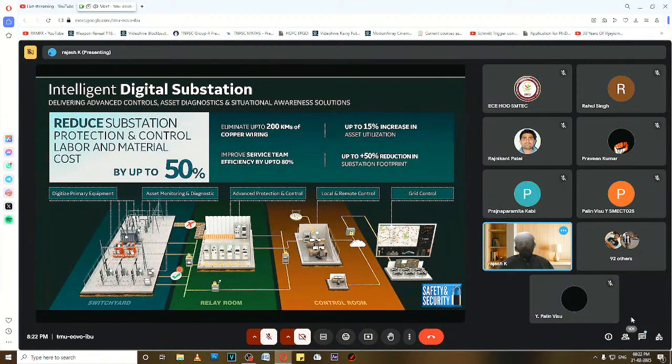Then we switched to monitoring and diagnostics in an advanced digital substation using several sensors, like temperature sensors, moisture sensors, and dissolved gas analyzers for the various gases which cause damage to the transformers. And we discussed the OLTC, and thermal cameras as well. Hope you find it helpful and interesting. Let me know if you have any questions or we can discuss.